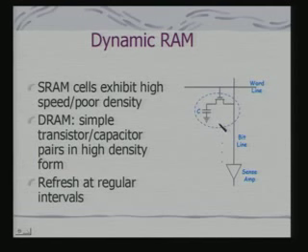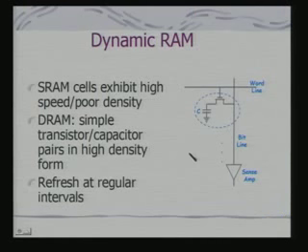But the only problem is I need to refresh it at regular intervals. Why do I need to refresh it at regular intervals? If I am storing charge in the capacitance, the charge will leak out. So, I need to refresh the charge on this capacitance at regular intervals. So, it is not that once written it is forgotten forever. Just like SRAM, as long as the power is on, the data would be retained, but this is not true for dynamic RAM because charge can get leaked out, so it needs to be refreshed at regular intervals.